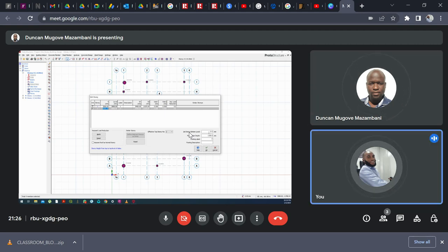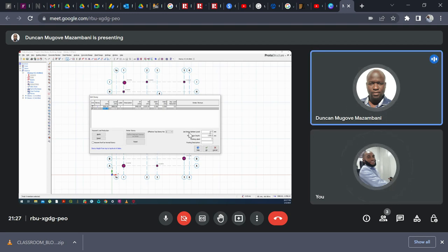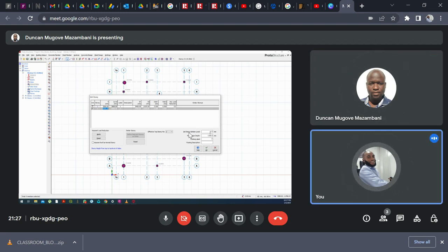As you all know, for a normal building, most DPC they use 450, they use 600, and most times 750, depending on the terrain of the site and the road being too low. If the site is too low from the road, you have to have a higher DPC. That's what I mean. So from here you can add the value of your DPC.